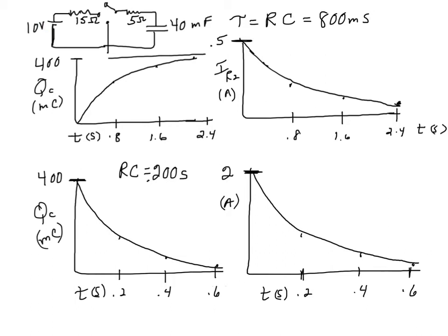And since this is 10 volts, the capacitor will charge until it reaches a voltage of 10 volts, and then it'll stop charging because the capacitor and the battery voltages will be equal and opposite. So it will charge to a maximum value of, let me write that equation, Q max will be equal to C times V max.